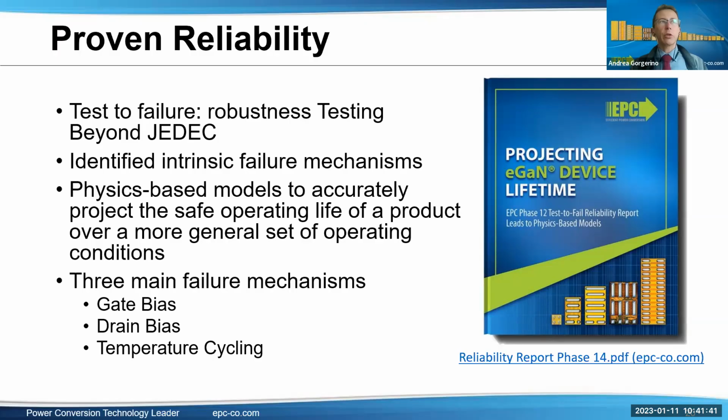And our customers have found that they were able to address the typical EMI requirements with very similar methods as the ones used to get silicon designs to pass. I would say, again, in some cases, there can be some advantages of using GaN FETs, like the fact that there is no reverse recovery, because that is, for example, a very large contributor to EMI noise that is not present here.